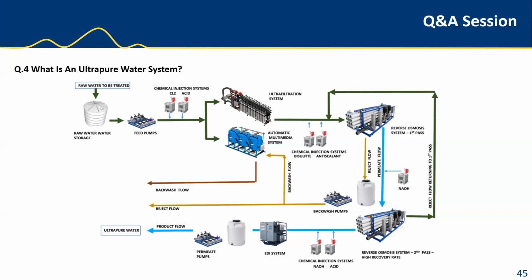Finally, the last and most important but sometimes expensive step is creating ultra-pure water. In this stage, ultraviolet light and heat exchange is used to control the temperature in the ultra-pure water supply. The non-regenerable ion exchange coupled with membrane degasification and ultrafiltration are used to truly filter the water down to the necessary particle levels. After these three stages, the ultra-pure water is ready to be utilized in your system, as we see the output stage here. Quite a nice little graph that we have here.